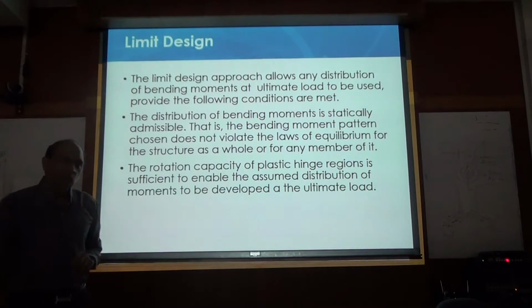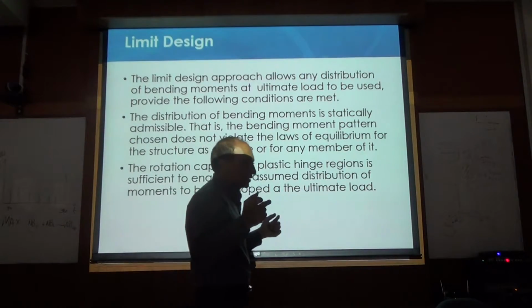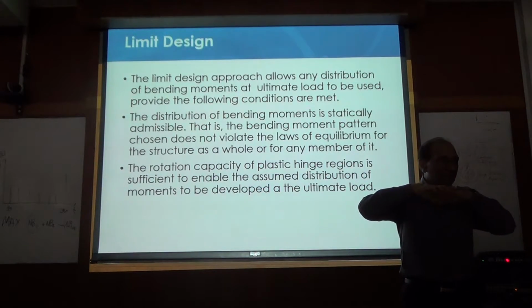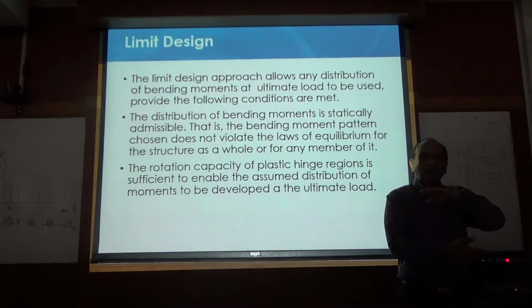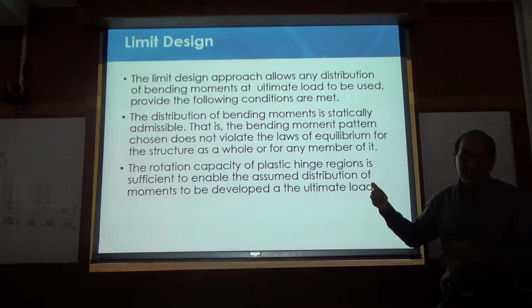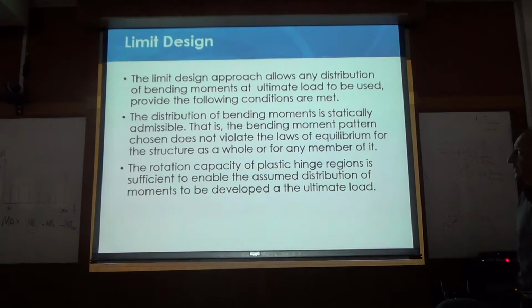So that way you can reduce reinforcement congestion, because normally at the top of the beam there are a lot of rebars. If you cannot fit them, you take out some bars and put them at the bottom and let it yield, right? So that is coming from this concept that we are talking about, yielding.